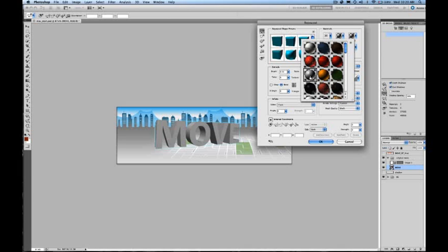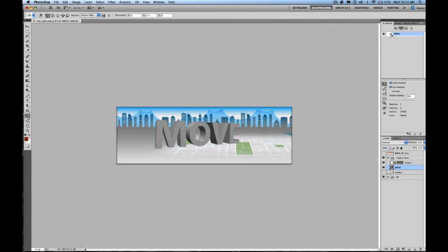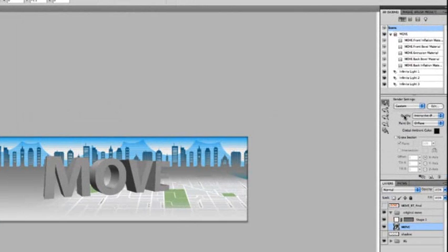An important note, most materials will need to be rendered using the Adobe Ray Tracer to see final lighting and optimal rendering. To kick this into the Ray Trace mode, go to your Scene Graph, and under the Quality menu, choose Ray Trace Draft or Ray Trace Final.